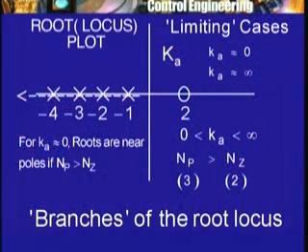If Np is less than Nz, the situation will be reversed. The number of branches will be the degree Nz, that is, of the zero part. The branches will all end at the zeros, but Np of them will start at the poles, and the remaining will start from a region of the z plane which is very far away from the origin, and therefore they will sort of come in from infinity, starting very close to asymptotes again. So one can find out the position of the asymptotes in both cases.